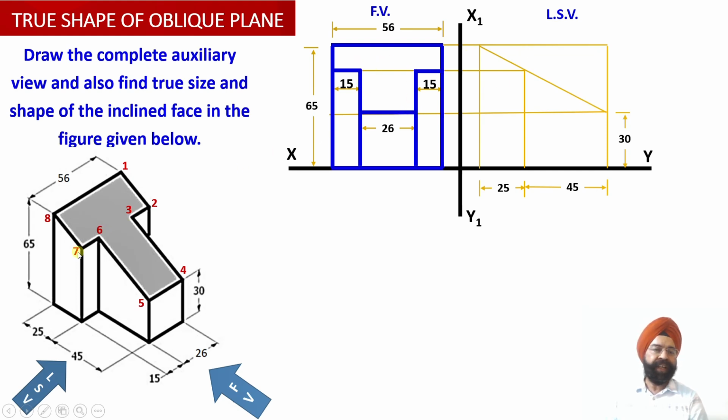Now second, we have got this vertical face over here. So this vertical face happens to be parallel to the vertical plane. So the projection of this rectangular surface onto the vertical plane will represent its true length. This surface is also true length because this surface is again parallel to the vertical plane. And finally, this surface also happens to be parallel to the vertical plane.